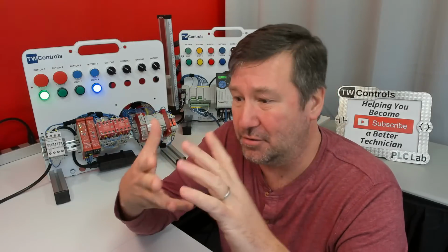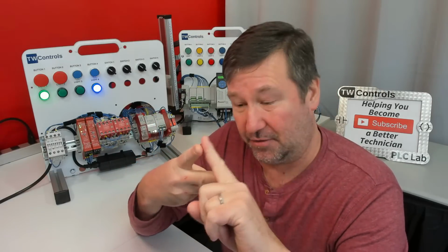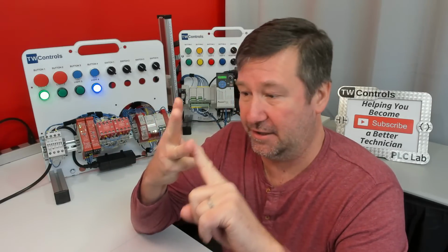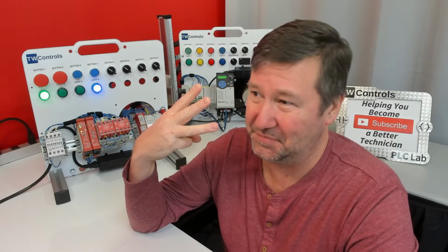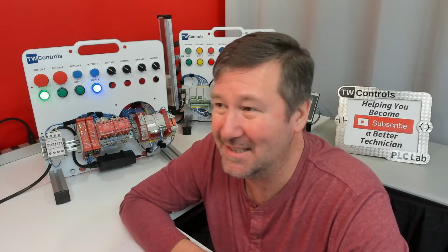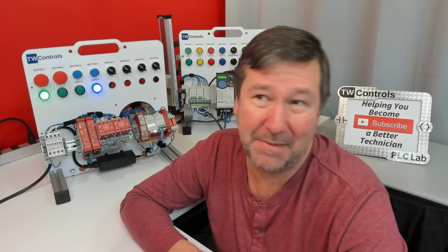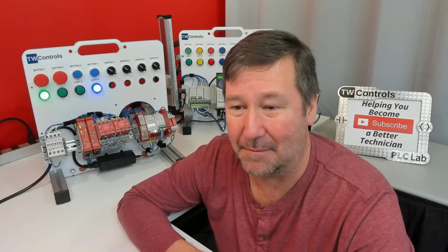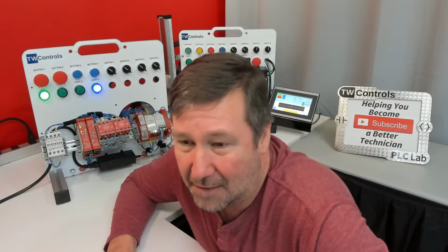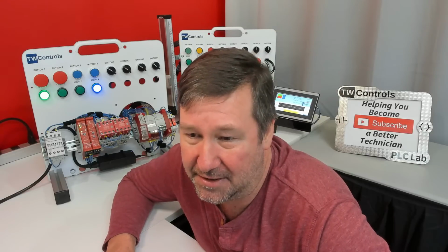And those go look for one, go look for zero, output energize instructions. If you know those three, then you can bumble your way through probably at least half the programs out there, maybe 60, 70% of them. So that goes through that and then hits timers, and that right there will get you a pretty good ways.